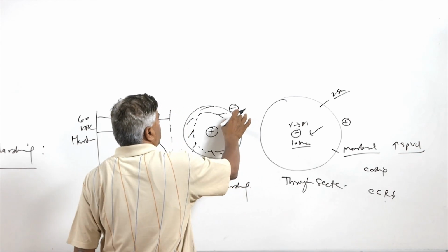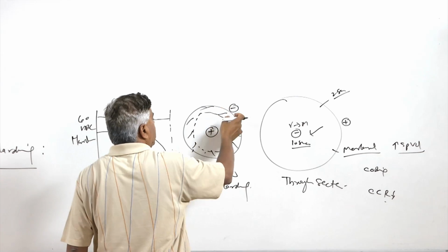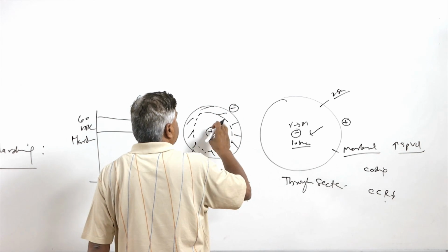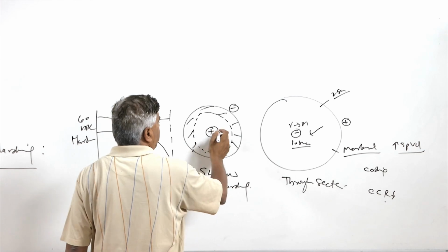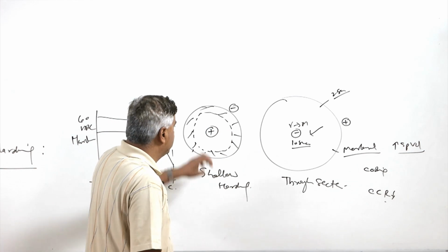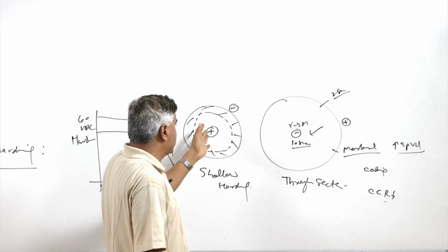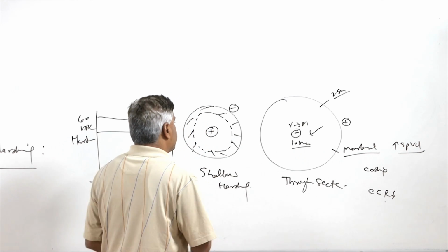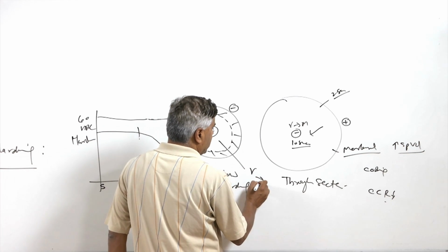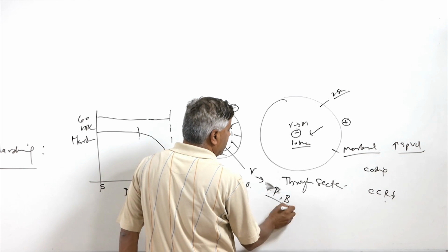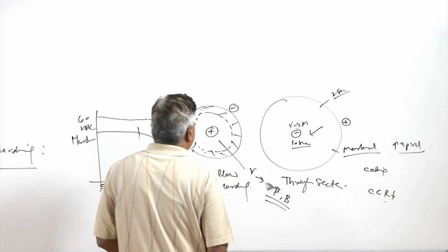In the shallow section hardening, the surface gets hardened, and subsequently transformation doesn't occur into martensite at the center. From the austenite it occurs into the pearlite or the bainite, so it doesn't occur into the martensite.